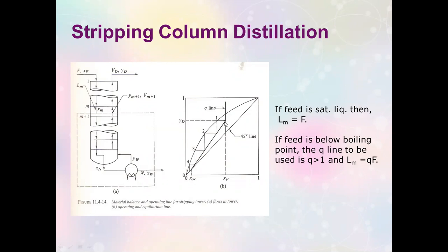Why are they all equal? Recall that your distillate just came from the vapor that was condensed. So whatever the mole fraction of the vapor is, that should be the mole fraction of your distillate. And if there's reflux, that would also be the mole fraction of your reflux.